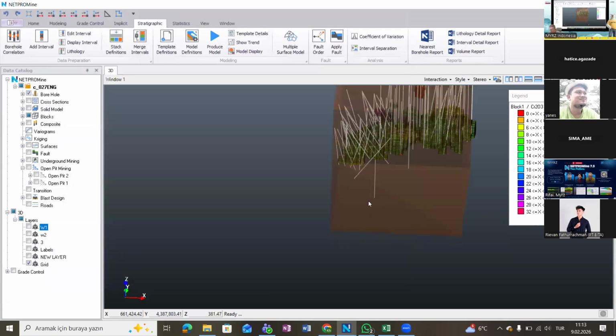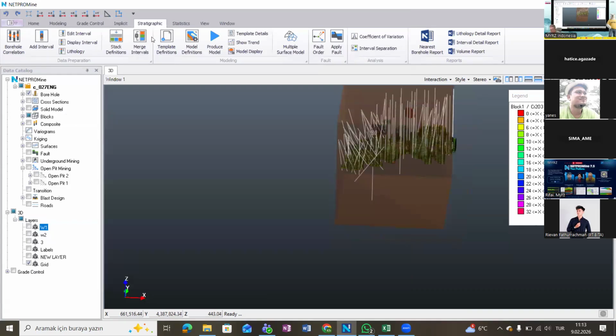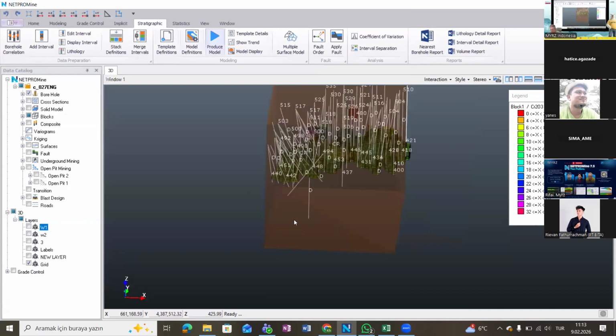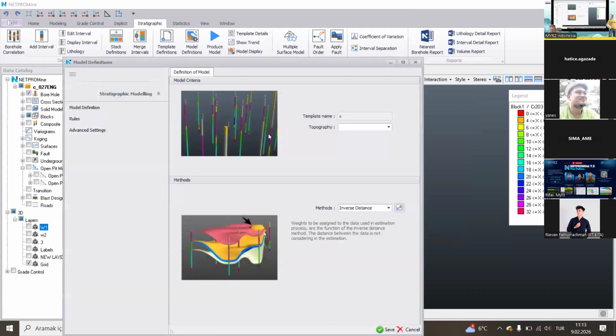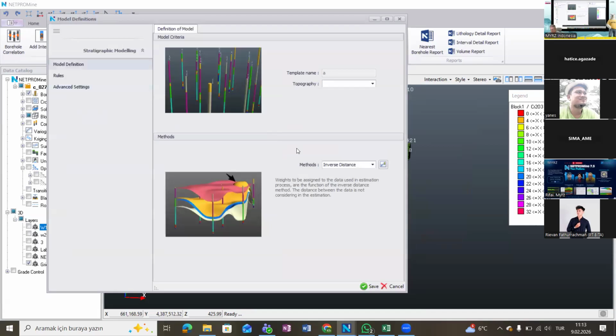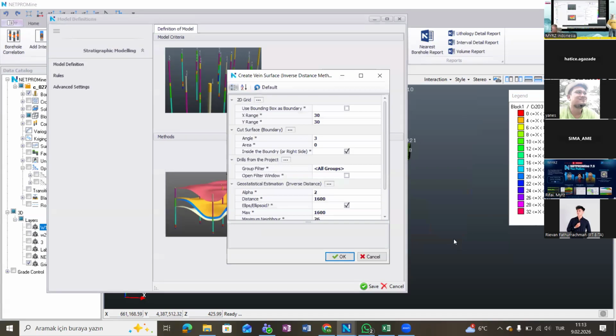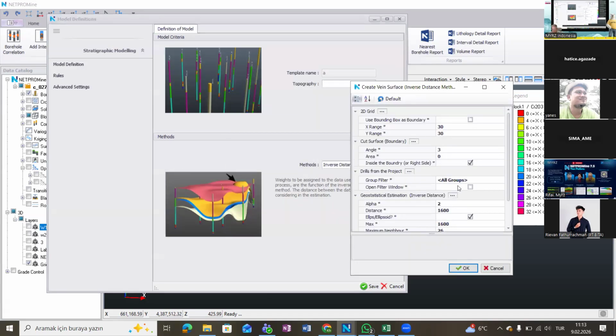It can give you directly the solid model, which is calculated in 3 methods. So you can give the restriction to your triangulation here to make it more precise, or you can draw the area and define the area here in settings, so it will not go further through your limitations.